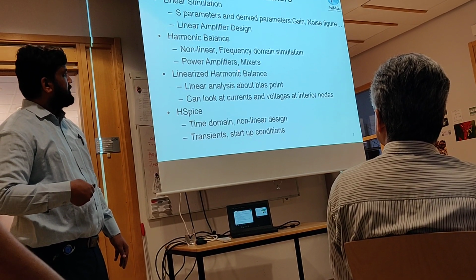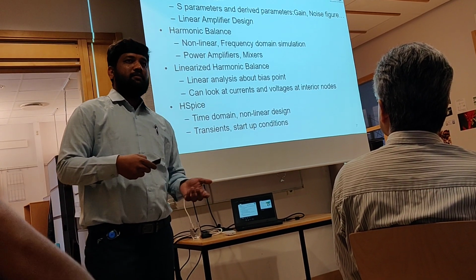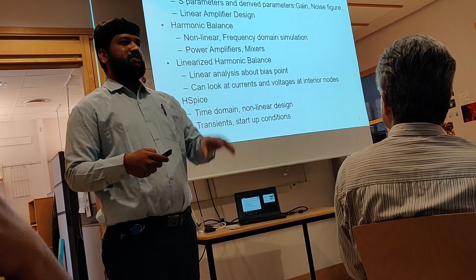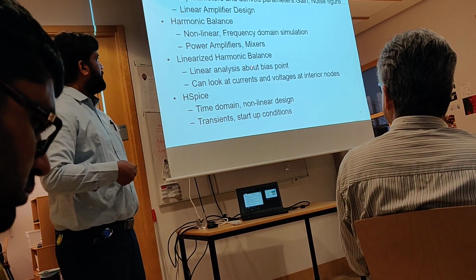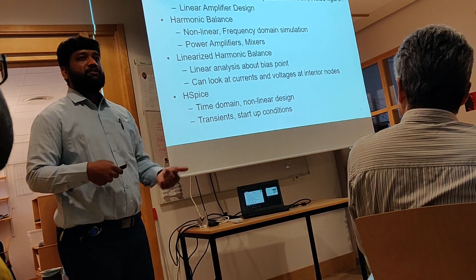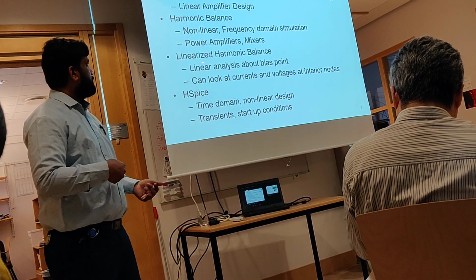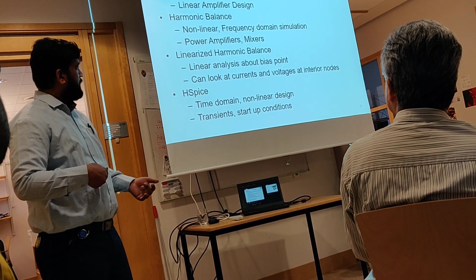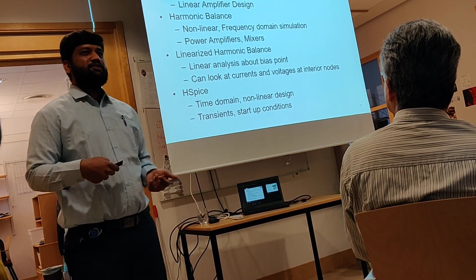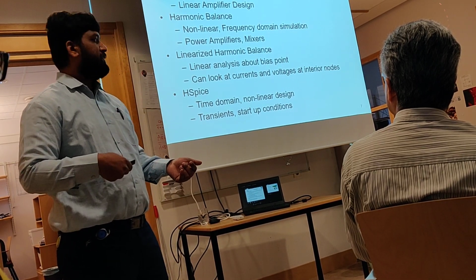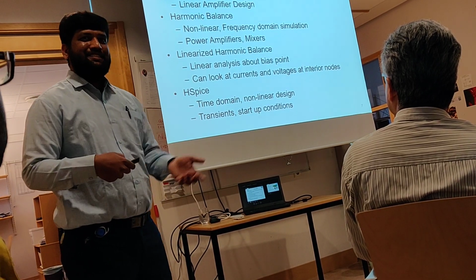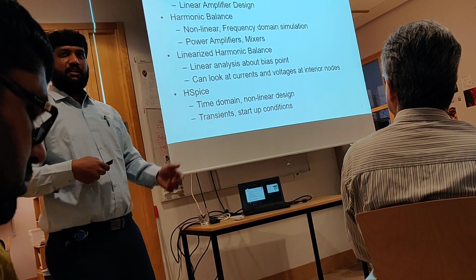Linear harmonic balance, this one, is used when you are playing with some of the active devices where you want to judge the biasing point and different DC levels, and different current levels or internal nodes have to be examined; most we can go with a linear harmonic balance method. And HSPICE is just an advanced version of a SPICE model. So it can handle some non-linearity design, and it can handle some oscillation startup conditions and transient analysis.